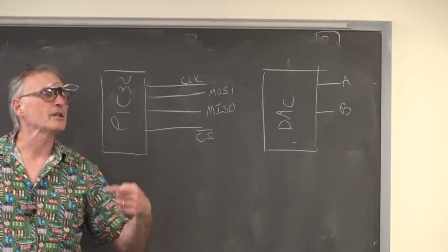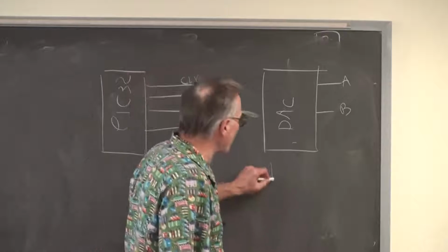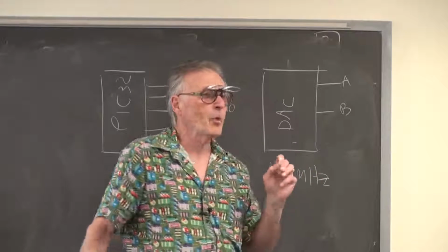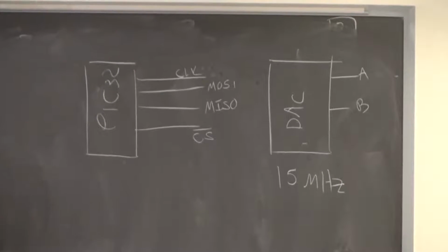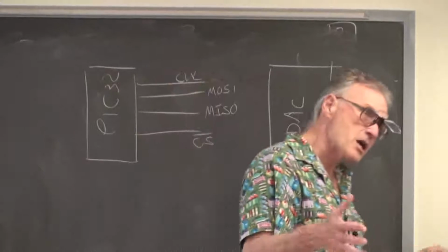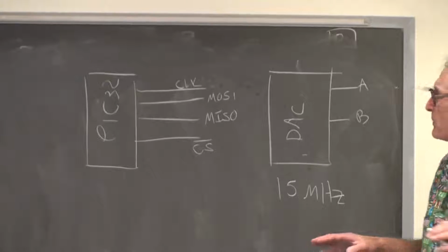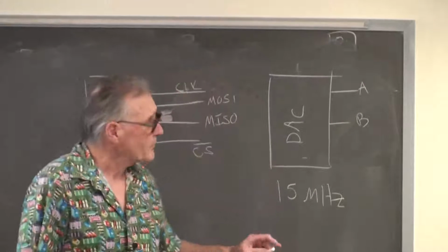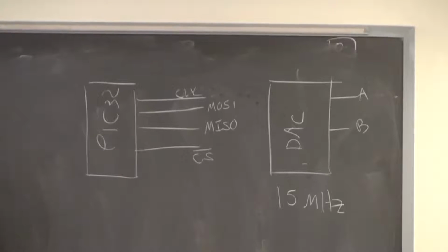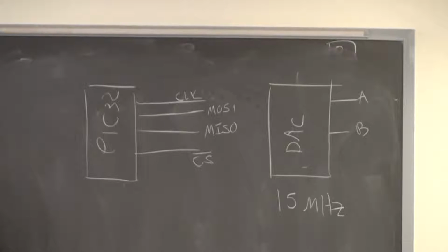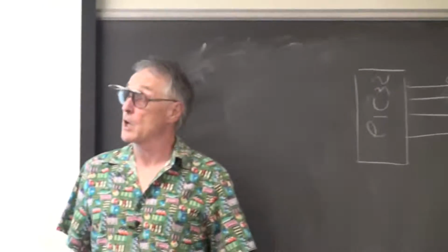The whiteboards behave a little better if you run the SPI channel at 15 megahertz because the bandwidth limit of the whiteboard is right around 20 megahertz. Above that, it's a short circuit. So if you leave it at 15, you get a little bit better looking clock response. Over this port, you can sequentially send channel A and channel B. It's a serial line. Each channel update is 16 bits. Running at 15 megahertz sounds like 1 per microsecond.